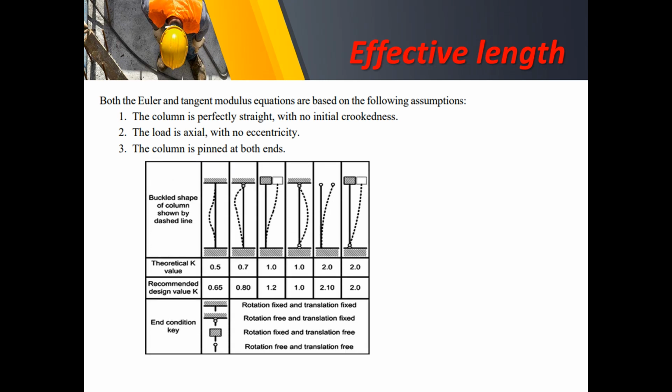So that is given by this diagram, wherein if we have a different configuration, there will be a theoretical value. First, we have a fixed-to-fixed end support of our column. And then we also have the combined fixed and hinge connection, and then a combined fixed and a roller allowing horizontal displacement on the other side.